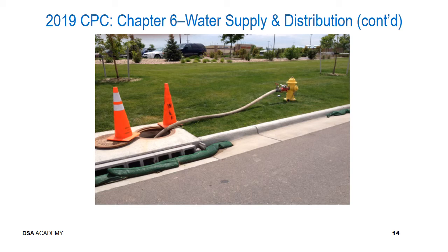And there's just no telling where the end of that pipe is, and there's just no guarantee with this particular connection that backflow prevention is even being implemented. So this is certainly a prohibited connection and cannot be allowed to be connected.